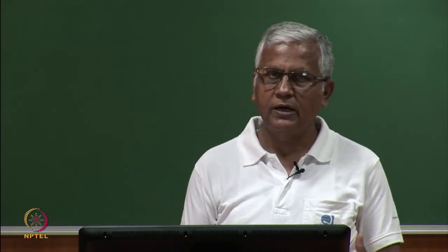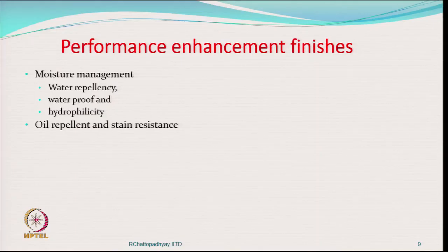Hydrophilicity may sometimes also be important, that is, we want to impart a finish through which we will be able to absorb a certain amount of moisture. Some fibers are very hydrophobic in nature, or their moisture content is very low. So, for these fibers, if we want to improve their moisture capturing capability, then a hydrophilic type of finish can be used. The other one is oil repellent and stain resistance finishes, which are also available.